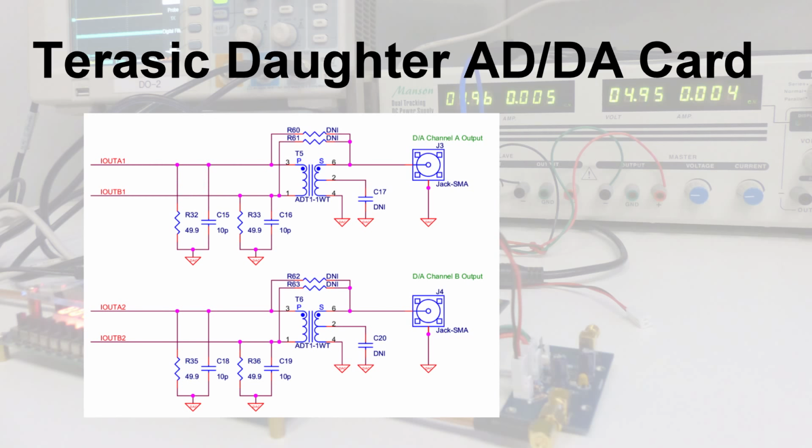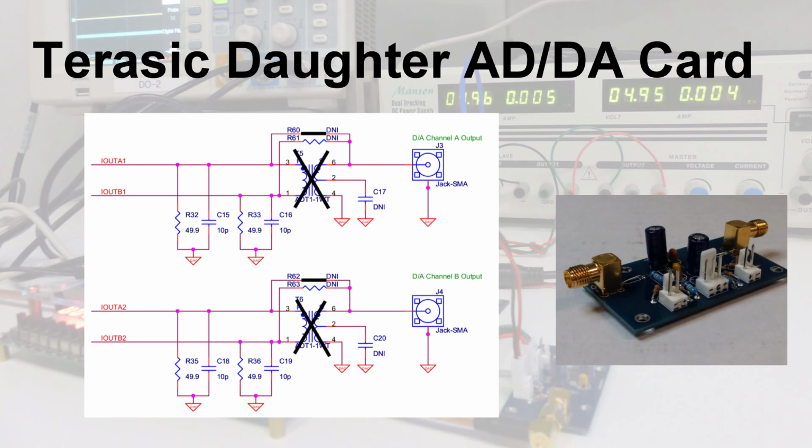The unfortunate thing about this card is that it has a couple of transformers on its inputs and outputs. This isn't helpful for us because we want to be able to demodulate a signal which is fairly slow, and these transformers restrict our frequency range to high AC. To overcome this issue, we removed these transformers and created single-ended outputs until we designed a printed circuit board, and I'll discuss this later on in this video.